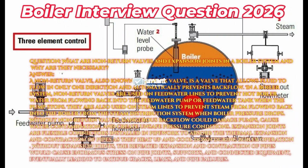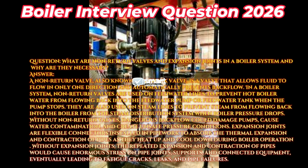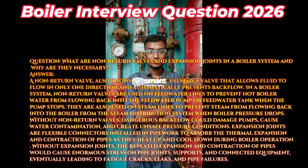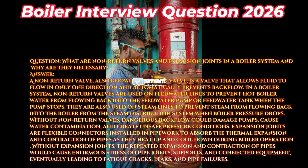Question: what are non-return valves and expansion joints in a boiler system and why are they necessary? Answer: a non-return valve, also known as a check valve, is a valve that allows fluid to flow in only one direction and automatically prevents backflow. In a boiler system, non-return valves are used on feed water lines to prevent hot boiler water from flowing back into the feed water pump or feed water tank when the pump stops.